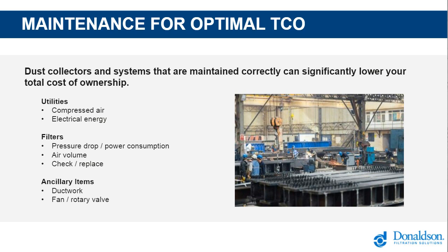Making sure that you use high quality filter specifications at lowest pressure drop and maximum efficiency. And then going again also to those ancillary components, making sure all the other components are checked and they are keeping the lowest cost of ownership. Block ducts, rotary valves, a thorough inspection is totally key to effective and quality maintenance.